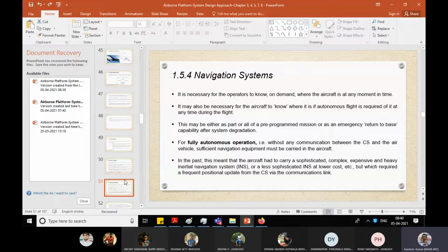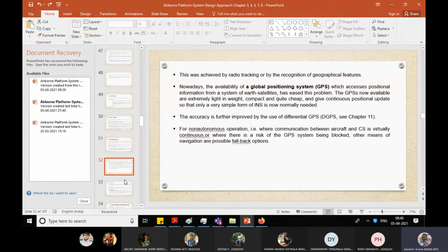So if you want to update the INS information, you should have calibration information available there itself. So there was a need to get an external source to calibrate that. I think that is when GPS came into the picture. Today you have GPS, DGPS, RTK, server-client based GPS, many options. IRNSS is also there, at least for India, with an extended area. So those services are there.